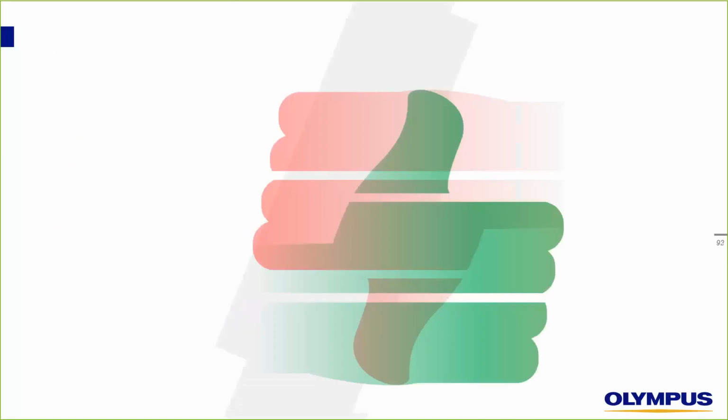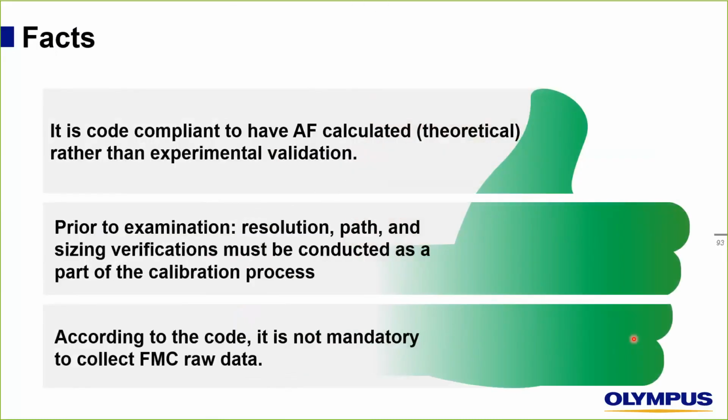Some facts now. It is code compliant to have amplitude fidelity calculated. So you use the theory to calculate the amplitude fidelity rather than experimental validation. This is absolutely true. Prior to examination, resolution, path, and sizing verifications must be conducted as a part of the calibration process. Absolutely, this is a new thing in the code, and it's a part of calibration. According to the code, it's not mandatory to collect FMC raw data, so we just answered that question, and this is absolutely true.